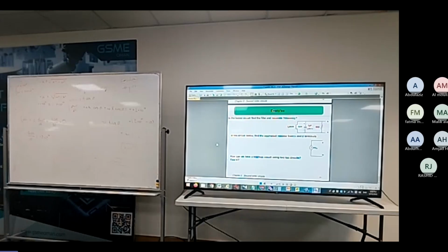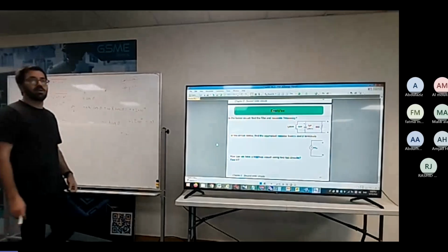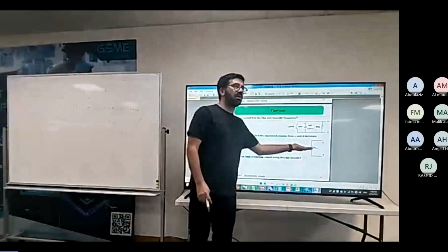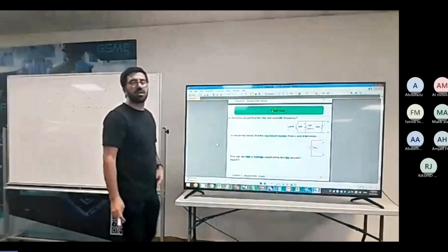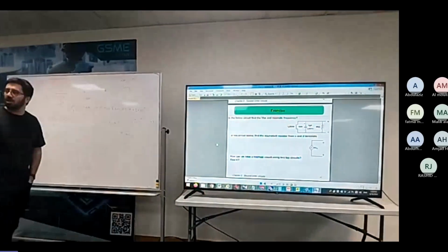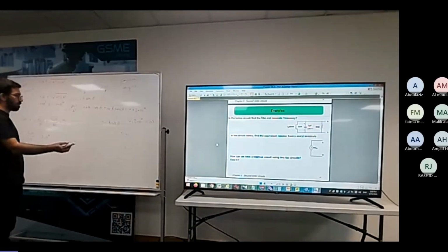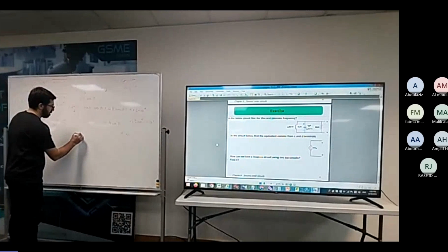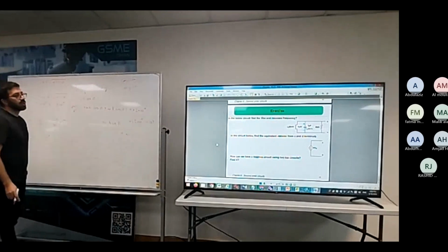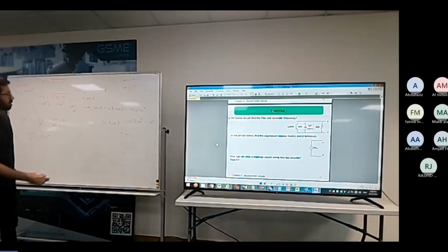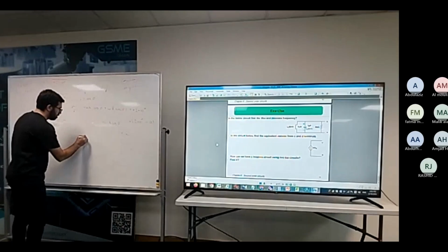What's the approach to find the equivalent resistor when they give you a complicated circuit and ask you to find the equivalent resistance of this circuit? Since it has dependent sources, we need to apply voltage and current, and we need to find the relationship between them. It is K I_B.